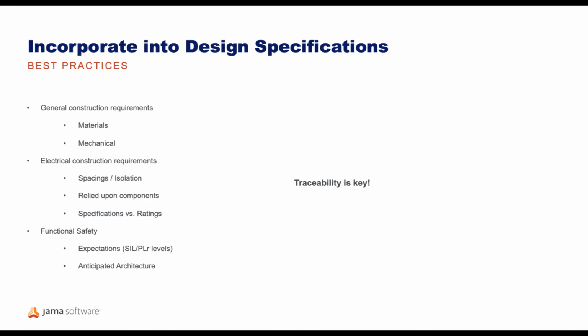Everything from the wire nuts holding two wires together or the connectors, all the way to the batteries and through the whole system with cooling systems potentially and other systems that make up a part of the whole system that you're looking to market. And so those general construction requirements are basically material type requirements, component requirements, mechanical requirements, and all of them are specified or delineated in UL 9540.